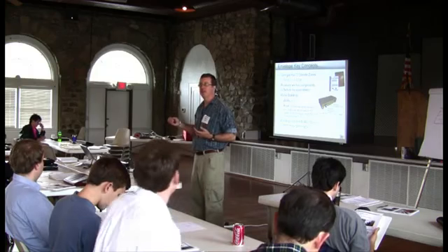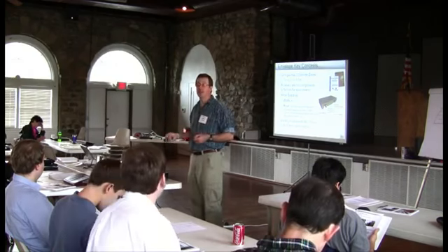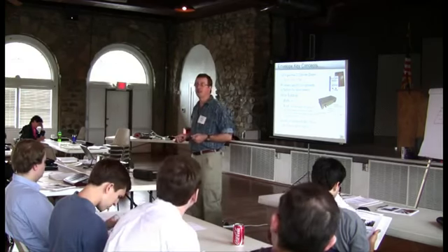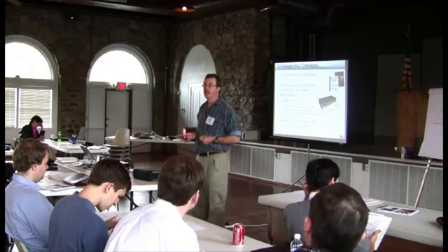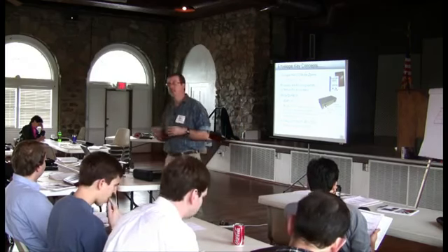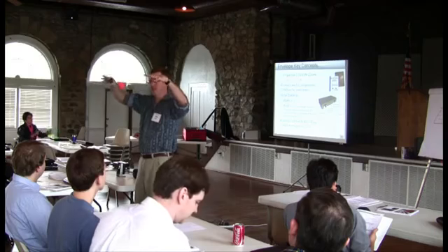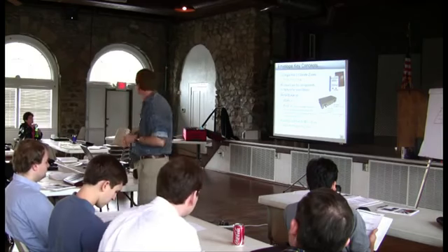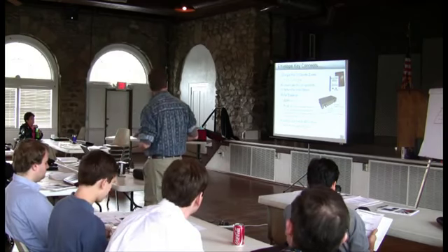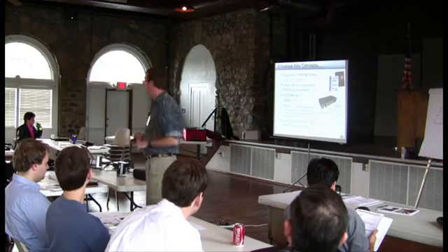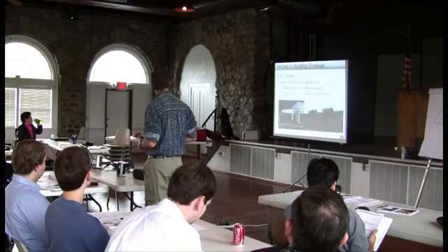But that statement is probably in the code. That's the key. R19 is what they want in essence in the field, and they want at least R10 at the purlin, so with a thermal block.